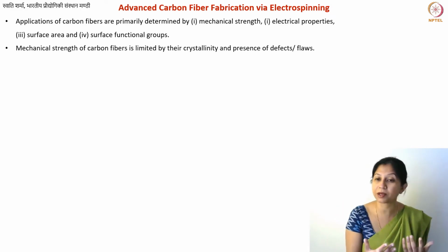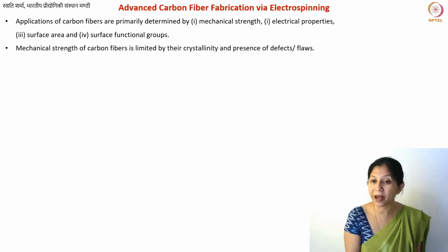You have different possibilities of arrangement of crystallites in carbon fibers, so it is slightly different from the bulk carbon materials. Also, the defect annealing patterns are different compared to bulk graphite, glass-like carbon, or activated, char-like carbons for that matter.